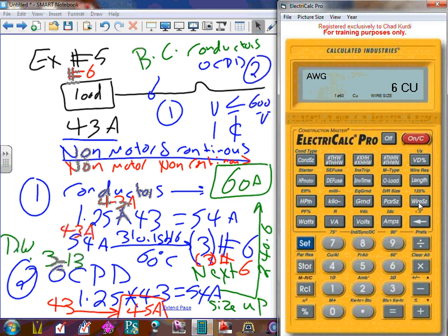Why does the rule tell you to go up for the overcurrent protection device? It's really the opposite. The rule of going up is the opposite of you can't load it more than 80% for continuous load, and then looking at the standard ampere ratings in 240.6.